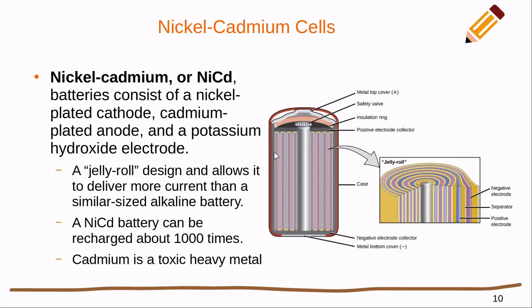And the second one being that they can start to lose charge when stored for long periods of time. That's the big difference between alkaline batteries and these types of batteries, right? I can put an alkaline battery in my TV remote, leave it there for 6 months. When I go on a trip, I come back, it still works just fine. If I tried that with a nickel cadmium or a nickel metal hydride battery, chances are it went dead while it was being stored there.